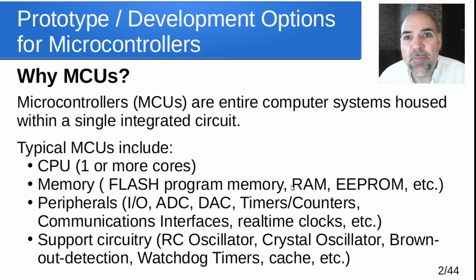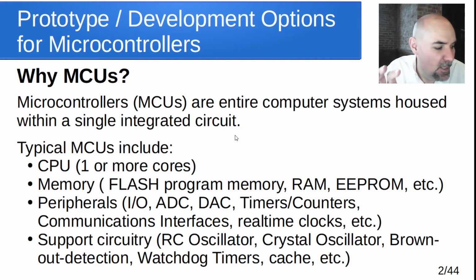If you're using this in an embedded system, the last thing you need is for it to lock up indefinitely and then not work anymore. So a lot of them have a Watchdog Timer capability to handle cases where something would have locked up. And then cache and other things are sometimes in there as well. So in other words, there's this really capable system on a chip with a whole bunch of different stuff.